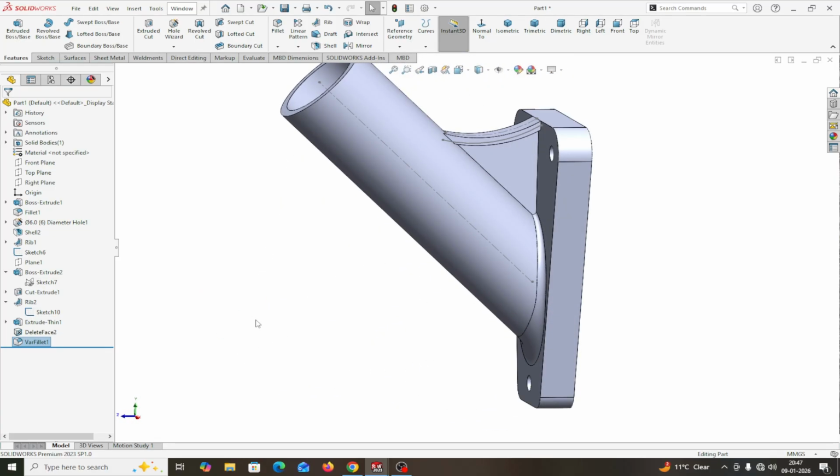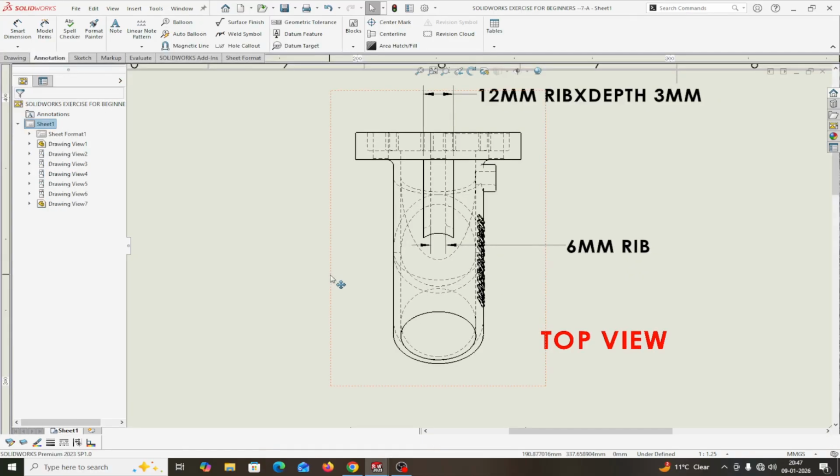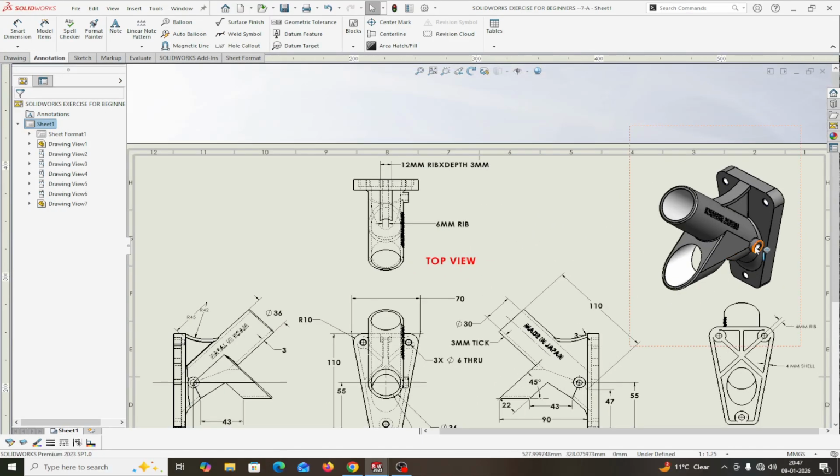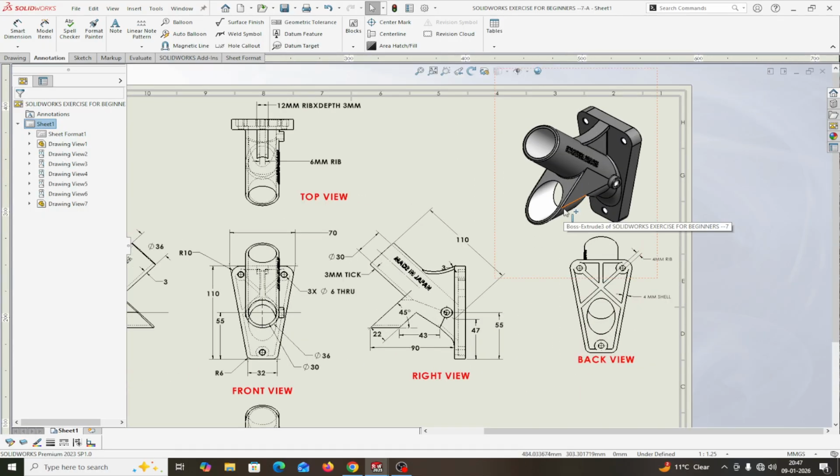Okay. Now if you see the drawing, now I will make this bottom one, this pipe, this bottom pipe, at a length of 90 mm. Actually, this portion is the straight portion, and this is at an angle of 45 degrees. You will see here, this portion is circular plus straight line. This portion is the straight, circular plus straight, at a distance of 40 mm.